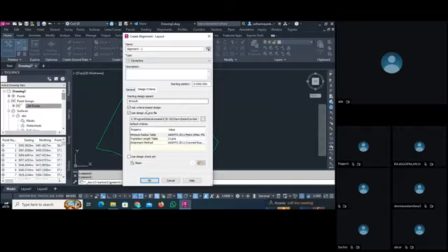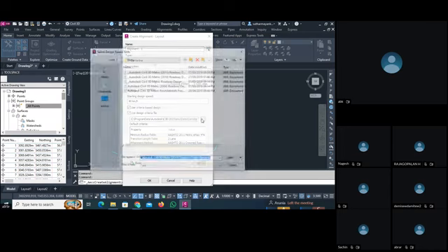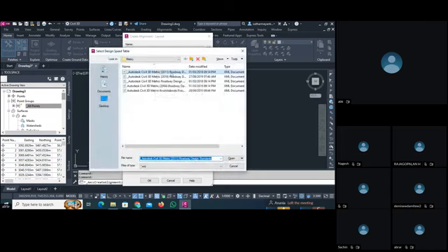See, what is this design about? If I choose the 80 kilometer per hour speed, Civil 3D automatically gives us some codes. So we have the 2011 code, 2080 code, road design 2004. It is all based on the AASHTO standard. And as I previously said, AASHTO is our green book. In every country code there is some difference, but not too much within the AASHTO code.